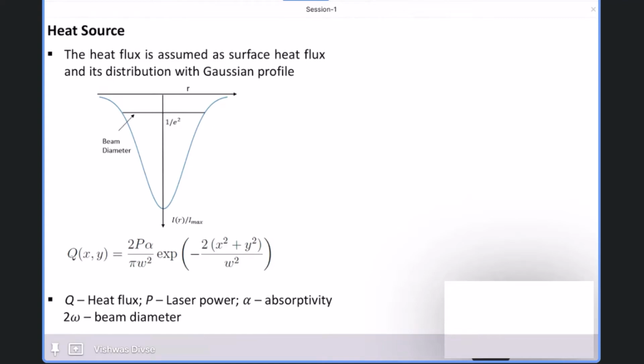The first thing in the understanding of laser heat source is the heat source itself. So various distributions are possible. If you have a laser set up experimentally, you might have seen they tell you the intensity distribution possible with the given laser heat source. They are like a flat intensity distribution, or the top hat type of intensity distribution.